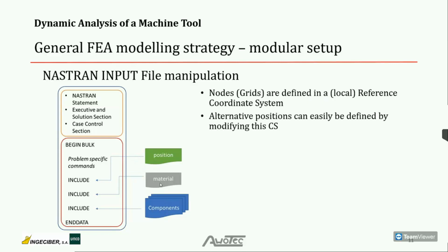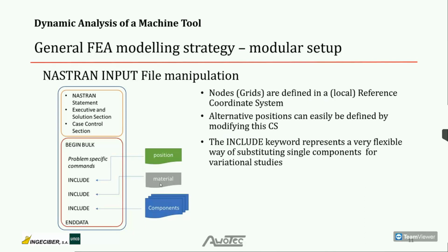components. And this strategy is very, very powerful when you set up a structure, a machine, with alternative positions of single components. And additionally, if you want to substitute one component with a newer revision of that component and so on, you only have to change each component file, which is the file where all the nodes and elements are included that are referenced by one component.